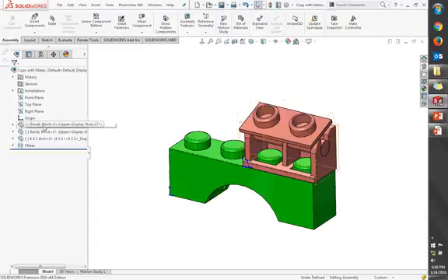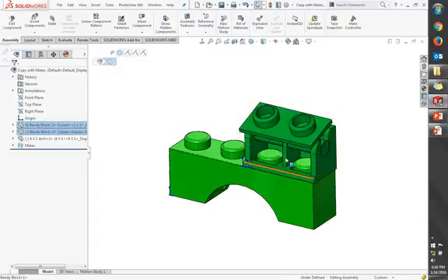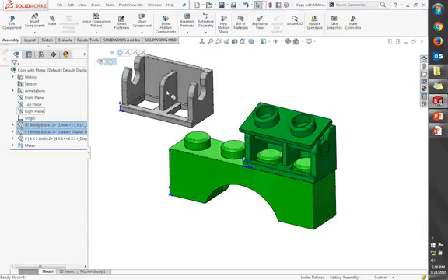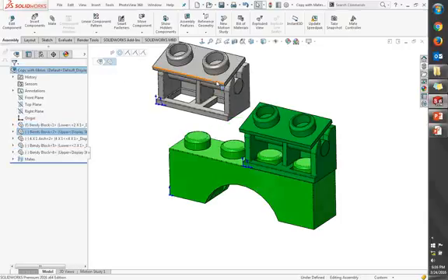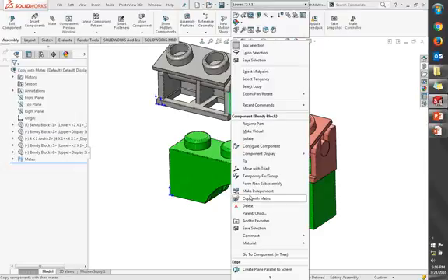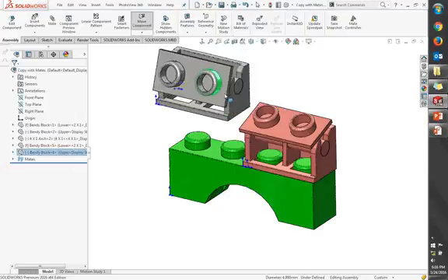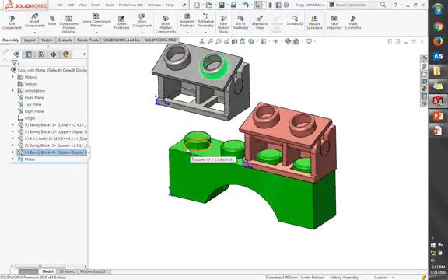What I can do here is actually pick the 2 components. You can do it from the screen, but I'm going to show you something that's a little awkward here. I'm going to hold down Control, grab the components and move them. Now, how many parts do you see there? You see 1 part, right? But as soon as we let it go, we'll see that the other part snaps into place. And if I just fix this real quick, just so it doesn't move around on me, you'll see that the mates actually got transferred as well.